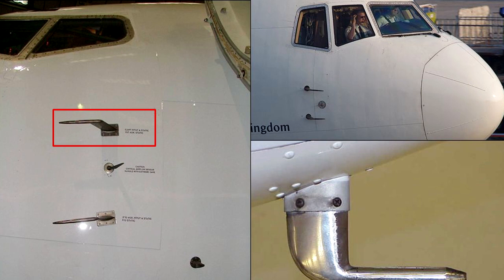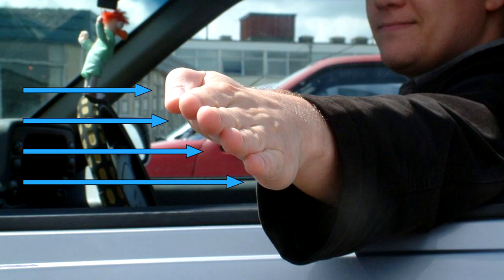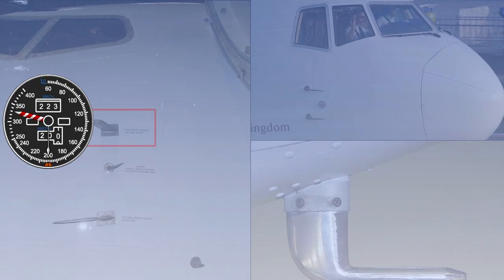These probes help us to isolate dynamic pressure on which indicated airspeed is based. You can feel total pressure by simply putting your arm out of the window of a moving car. However, total pressure probes, sometimes called pitot probes, and static probes suffer from errors. Without any correction to the errors, the speed which is obtained from the probes when dynamic pressure is being sensed is called the indicated airspeed, abbreviated to IAS.